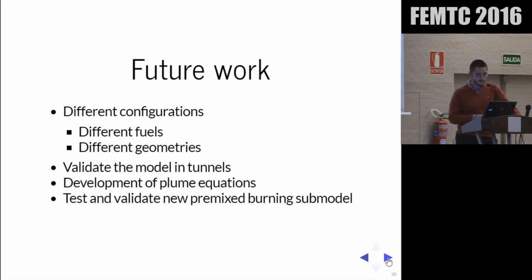It would be nice to have some plume equations for these premixed flames, like we have for the diffusion flames. And it will also be nice to try the new submodel that you can now find in FDS and see if the results are more or less the same.